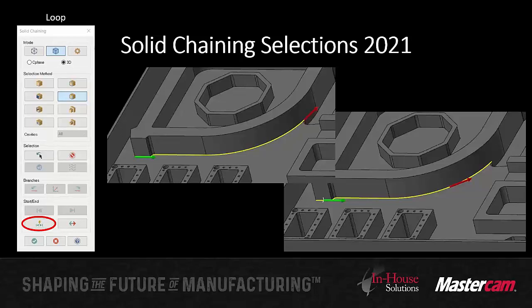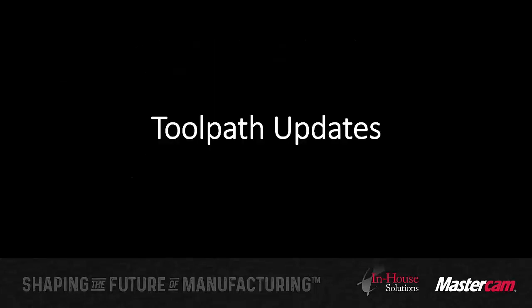So rather than having it start and end only at the beginning and end of that chain, I can select my chain, but I can then specify exactly where on that chain I want my toolpath, or whatever the case is that I'm doing, to end. So it can be really handy for your finishing operations when you're just trying to machine out a certain area, maybe making sure you're hitting or not hitting those avoidance areas with your tool, stopping short, various things like that. It gives you the option of, rather than using lead in, lead out, shorten by, and taking a quick guess of, well, it's probably going to be about 82% of my cutter, you can just specify exactly where you want to start and end. All right.